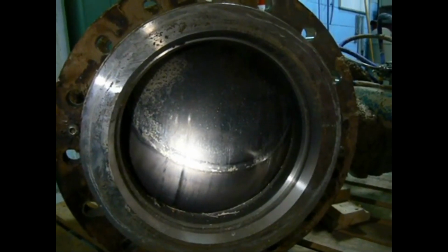Here we have a pretty large ball valve on a skid, and you can tell it's been in service for a bit. We took it out and were documenting the dynamic performance of this control valve because this was a brand new paper mill, and they were having control valve issues all around because some of the control valves were not up to par with what they should be doing. So we hooked up the air to the actuator and the positioner, with a 4-20 calibrator hooked up to the positioner, and we're slowly stroking the valve open and closed.